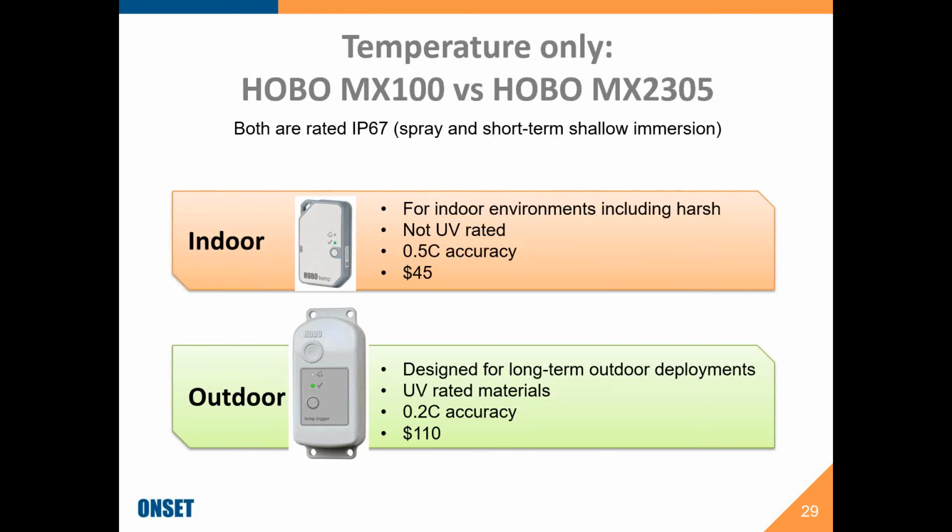If it's just a humid environment that you're operating in, I can't necessarily give you an exact number, but I think it'd be very reasonable to expect a 3 to 5 year RH sensor life in even high humidity environments. Again, it's proven to be a very reliable sensor. It's really only when it's been a caustic environment that we find people having to replace them, and that's why we didn't feel it was necessary to make the sensor replaceable, because not that many people have been having to replace them.